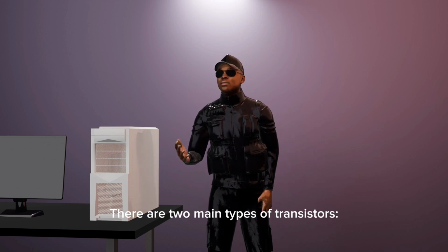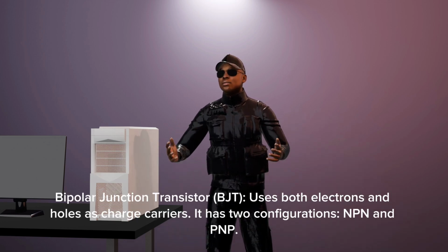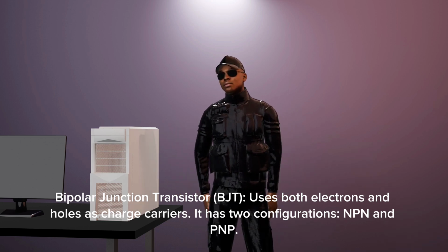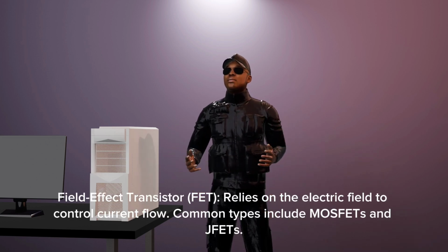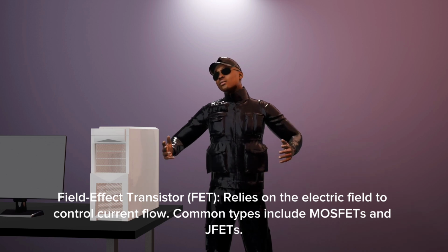There are two main types of transistors. Bipolar junction transistor, BJT, uses both electrons and holes as charge carriers. It has two configurations, NPN and PNP. Field effect transistor, FET, relies on the electric field to control current flow. Common types include MOSFETs and JFET.